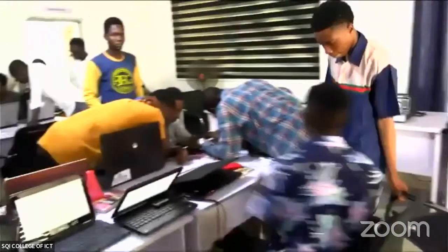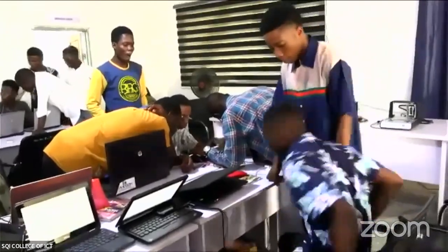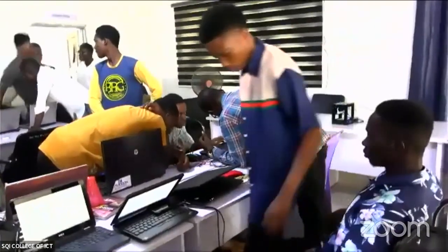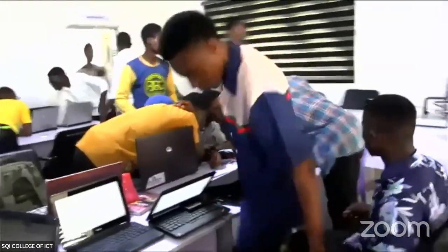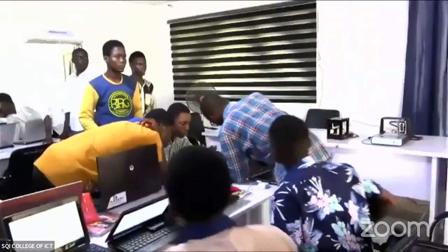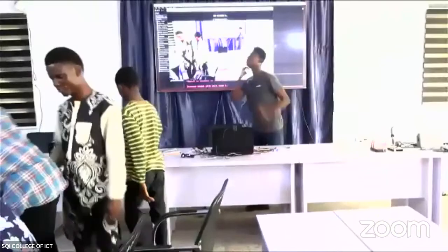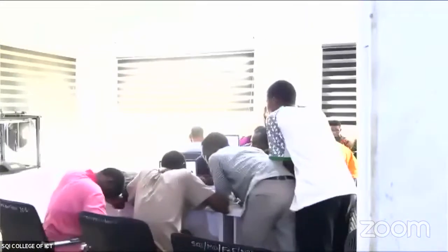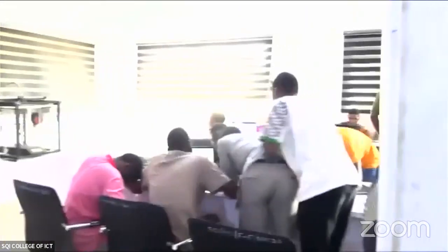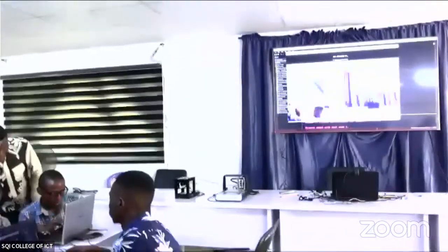It was too fast, so it was picking the values. Introduce a delay to your code, please, also after you press the button. If your connection is correct, you should have a series of ones being printed if you run your code. Even if you don't have the delay, if you run an LED blink and you press it, it's going to go off. It's just that the serial monitor cannot pick values that fast. That is why it's just showing one.